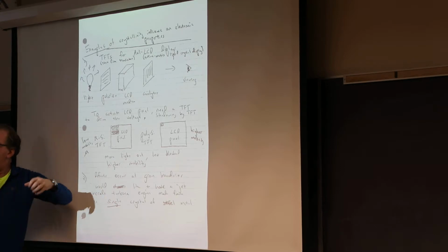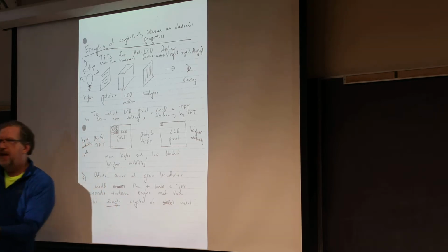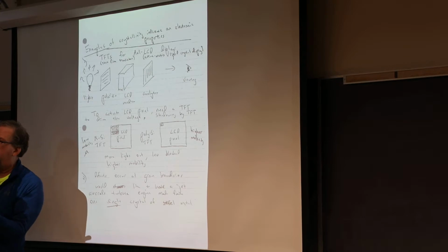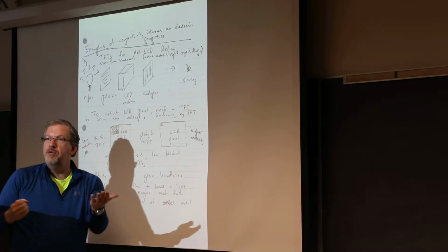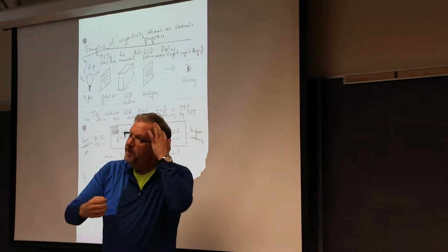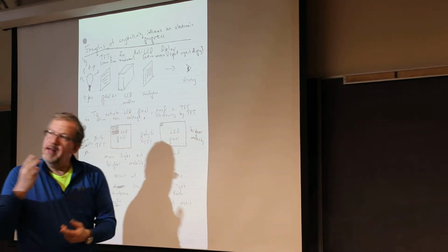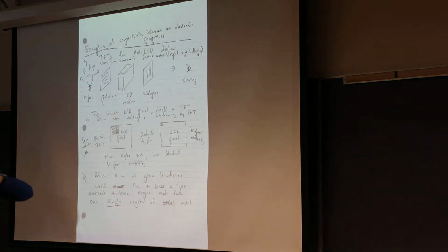When we play Jenga, the pieces come down and wherever they hit, they stick. Well, that means you lose Jenga pretty quickly. But what if I could hop things over? That's what epitaxy is. They can hop into those little holes and fill things up, and then it's crystallographically perfect. Heating the substrate allows the atoms to move around and minimize their free energy.